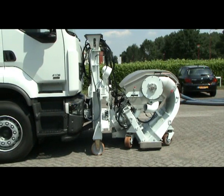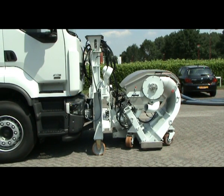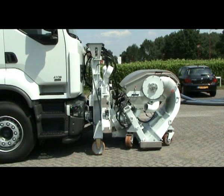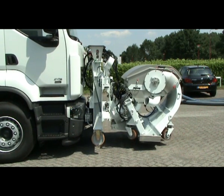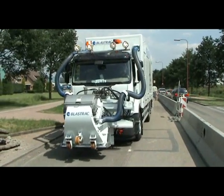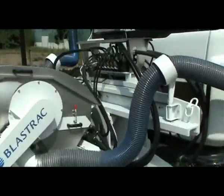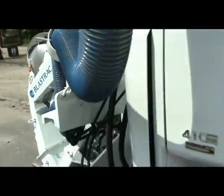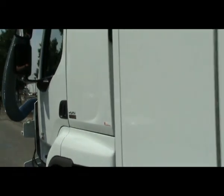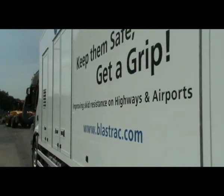Once the blast head is positioned in front of the DIN plate on the front of the truck, you only have to connect 4 hydraulic hoses and 1 electrical connector. The quick attach system takes care of easy and safe connection of the complete side shift and blast unit onto the DIN plate of the truck. Just by pushing one button on the touchscreen panel, you secure the connection with heavy sliding bolt system.